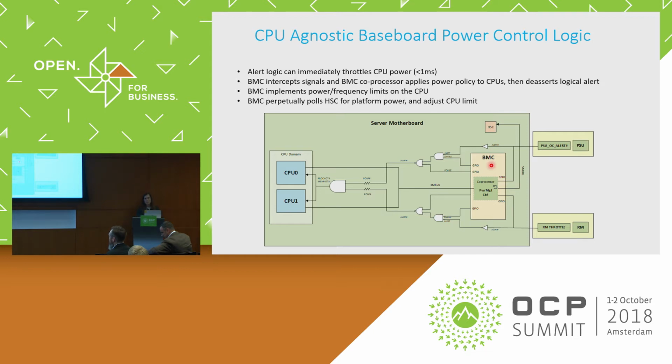And the rack manager is pre-installed with firmware also and gets updated through the fabric. It gets assigned a policy that says, this rack you're being deployed into is a 20 kilowatt rack. Don't let the infrastructure exceed 20 kilowatts. Or in the event of the row limit, it will divide up what the row limit is and say, don't let your racks cumulatively exceed these, and it will assign that policy to the row manager. So everything is configurably dynamic.